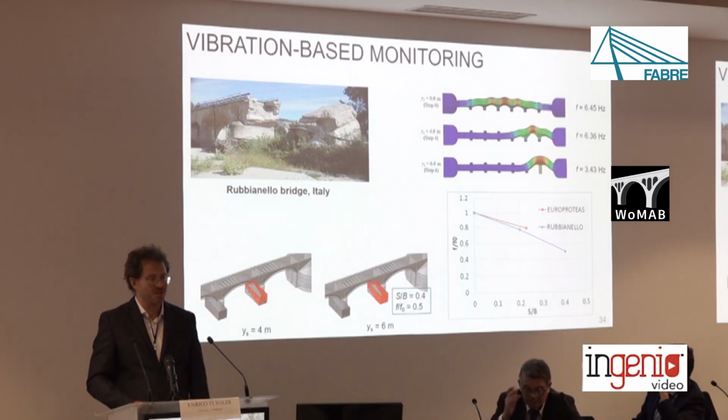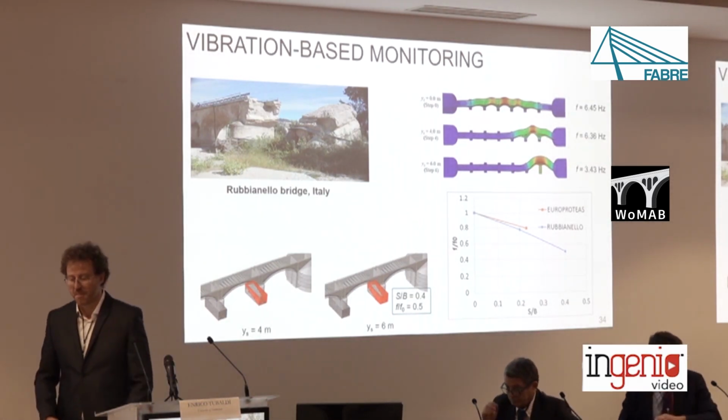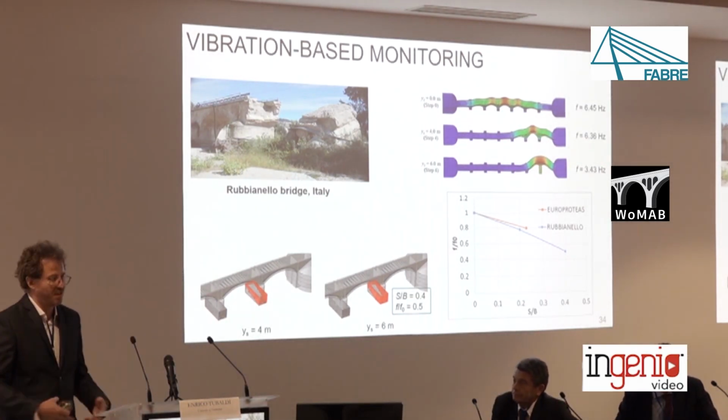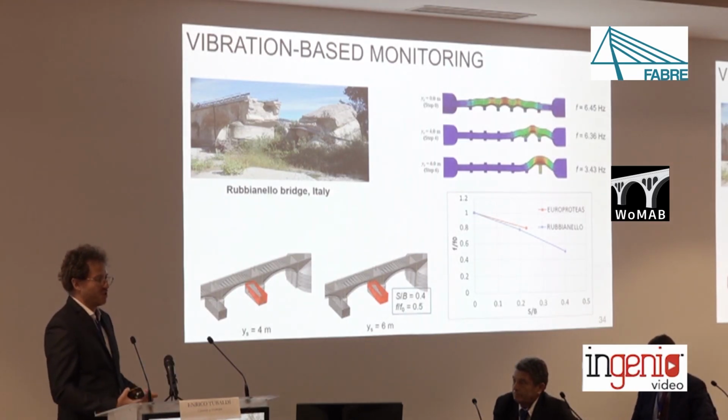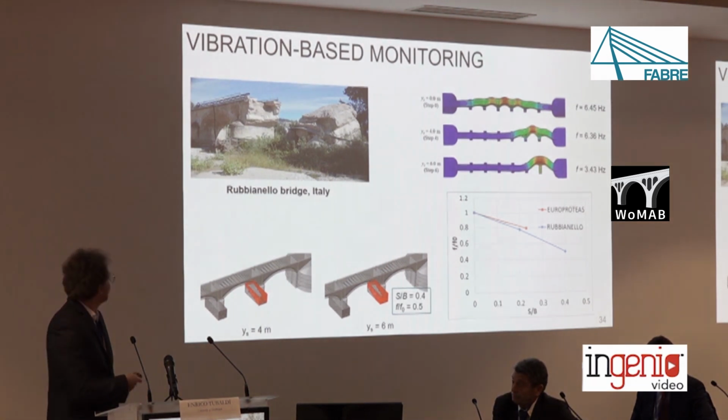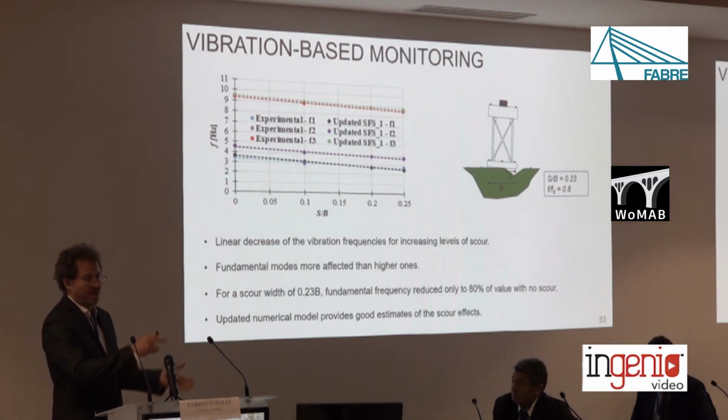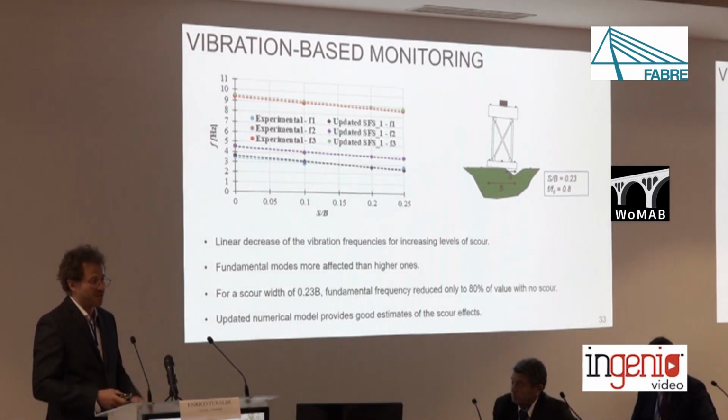this is expected because scour not only undermines the foundations and reduces the stiffness of the foundation, but also induces damage and cracking in the superstructure, which is not the case of this prototype here that behaves almost rigidly under the effect of scour.